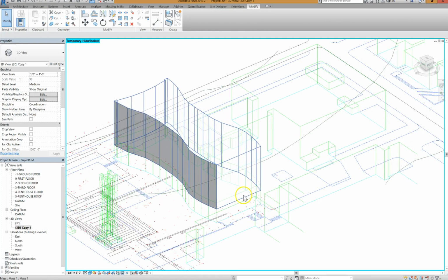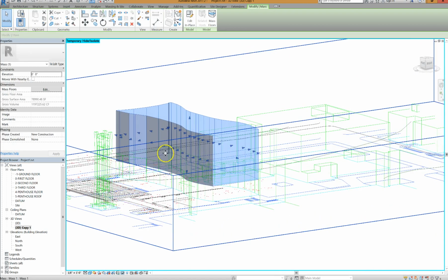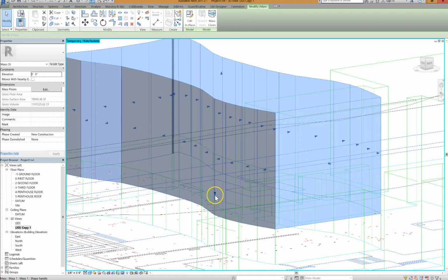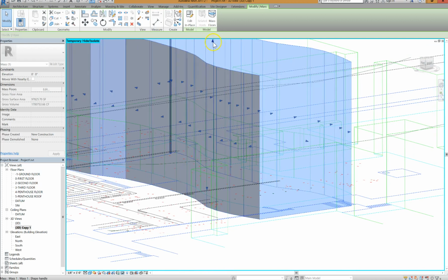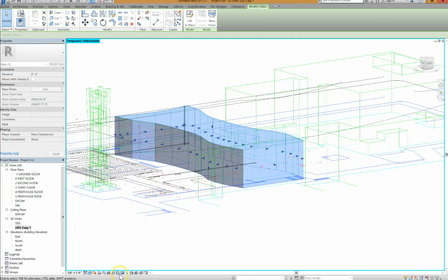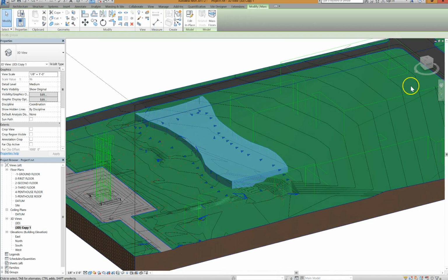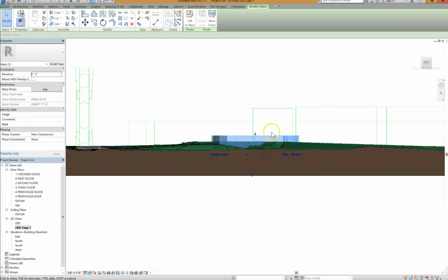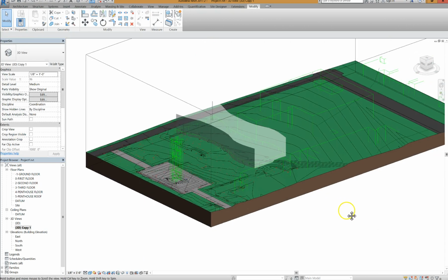Oh, that's right, I can't look at it shaded because I don't have the sight on. But then I have this mass that should roughly stick out of the ground the same amount as it is tall in the AutoCAD file. But again, I don't know the heights of these surrounding buildings very well. So I will turn off the temporary hidden space, and notice that I need to move this up a bit to get it above grade. Again, it's not the most precise thing in the world, but I am just tabbing up with my up-down buttons. And I have a building next to us.